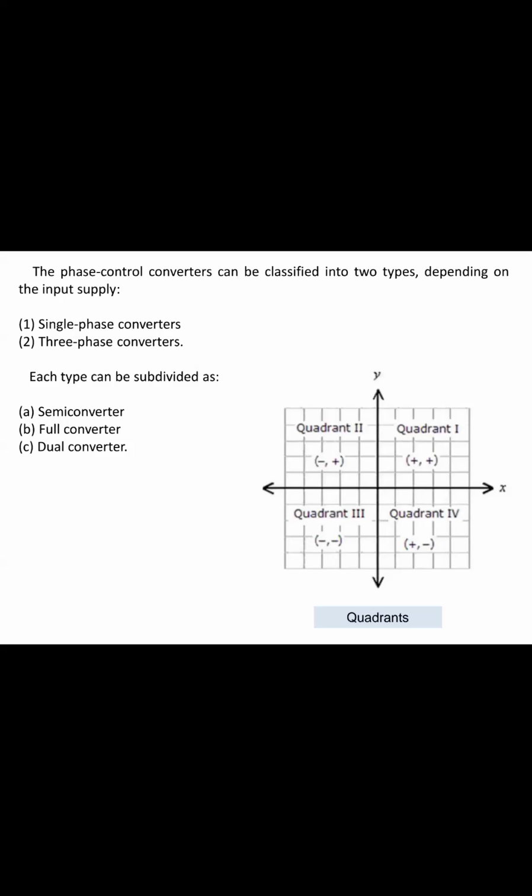And the fully controlled rectifier uses thyristors. We know the thyristor works in a controlled manner, so it is going to do the conversion of AC to DC. Fully controlled rectifiers use thyristors as the rectifying elements, and the DC output voltage is a function of the amplitude of the AC supply voltage and the point in the wave at which the thyristors are triggered.